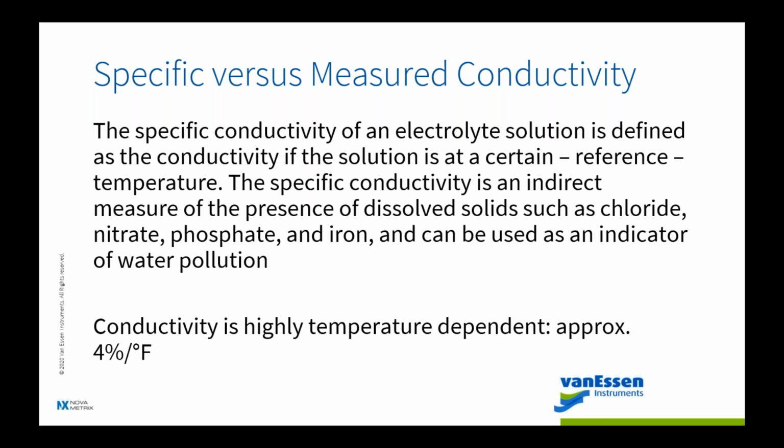So typically you'd want to select that method when you're in, let's say, a mining or a landfill leachate application, and you want to, for instance, in the case of a landfill, make sure that the liner's working. By putting CTDs placed strategically around the landfill in monitoring wells, you can certainly detect when the liner has failed and pinpoint, not precisely, but certainly approximately, where that leak is coming from.